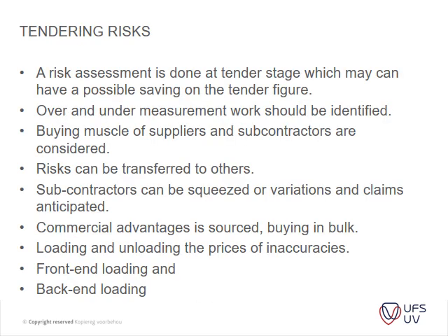You have to be very clear about that risk and try to mitigate it. Okay, then we get to tender risk, and this is a specific risk that's highlighted in more depth. A risk assessment is done at tender stage, which may give a possible saving on the tender figure. Over and under measurement work should be identified. You will see that on page 126.